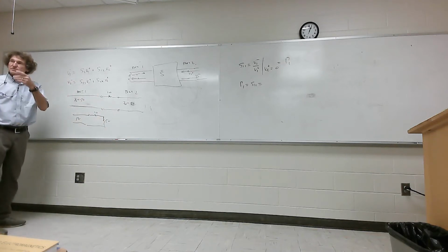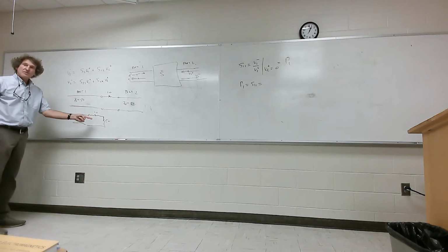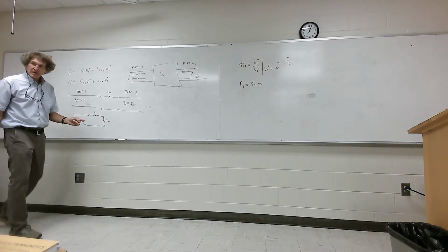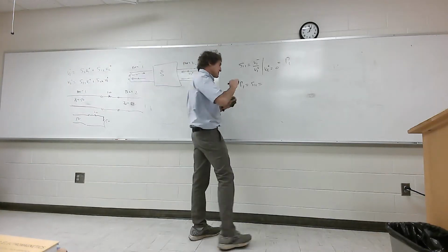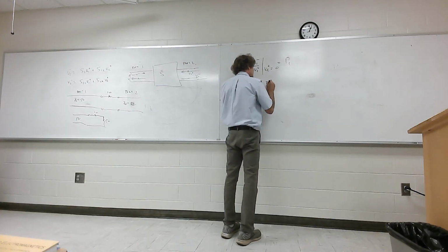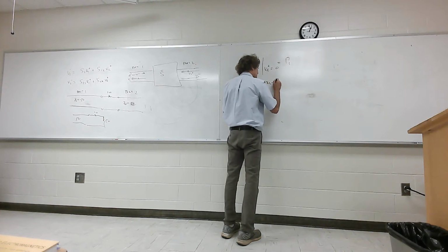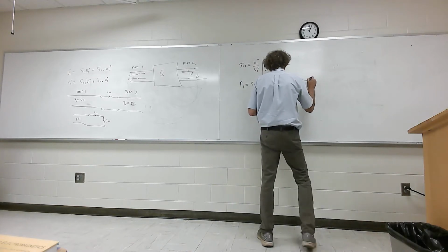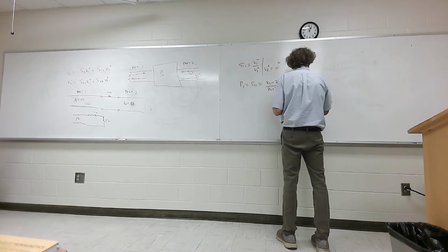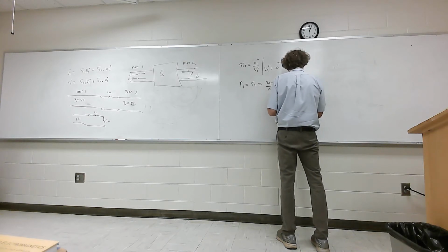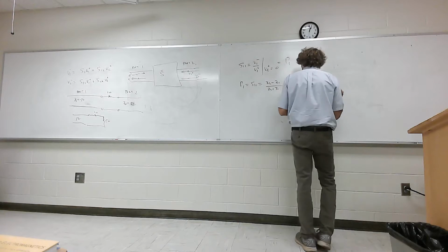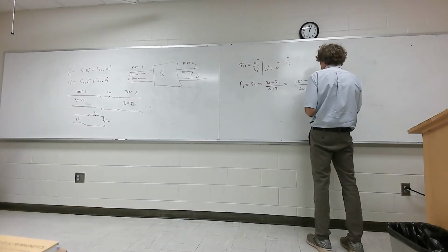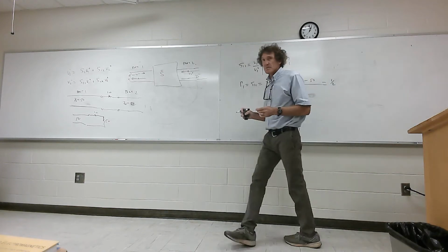Class, over here, it looks like I'm going into 150 ohms, and I came from 50, correct? So whenever you're talking about reflection coefficients, it's the impedance you're going into, I'll call it Z2, minus the impedance you came from, Z1, over the sum Z2 plus Z1. So for this one, Z2 is 150, right? Minus the impedance I came from, 50. The sum of those two is 200. So this has a reflection coefficient of really 1/2. Y'all follow me in that class?